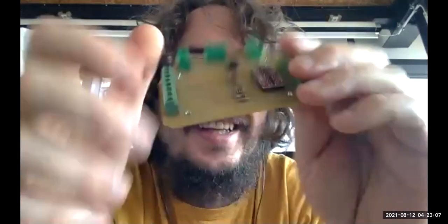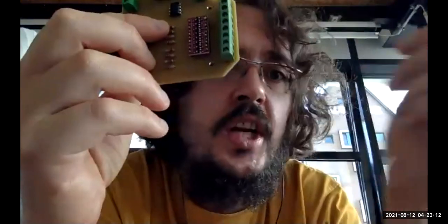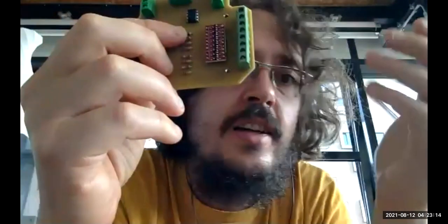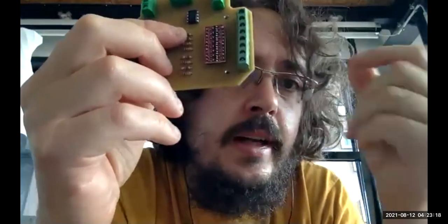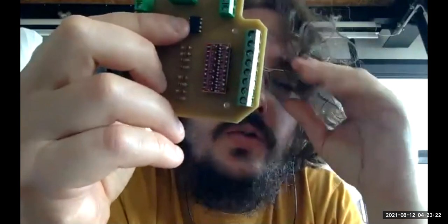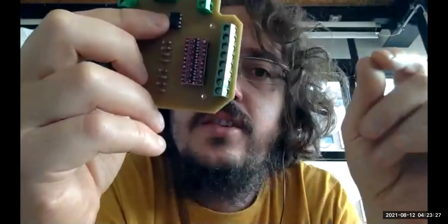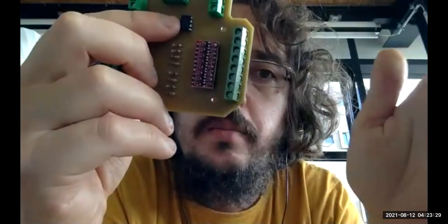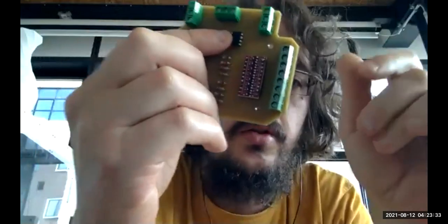So we discovered that the standard logic converter was not fast enough, and our engraving of pictures, which required several signals per second, were not happening. So slow cutting was fine, the others were not. There is also an ATtiny here on board that we use to drive a sort of safety switch for the machine, which is a relay. So there is a relay which cuts off the communication to the laser power supply, and it's driven by this microcontroller here.